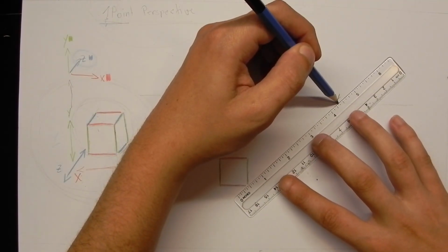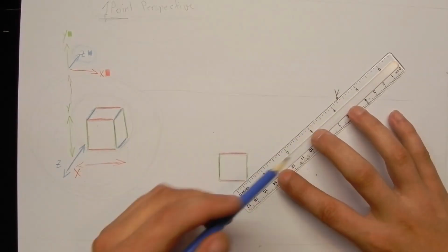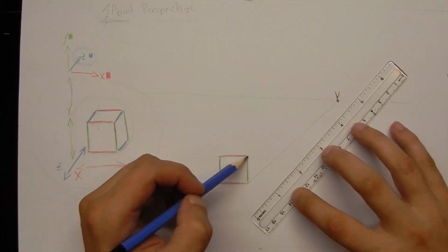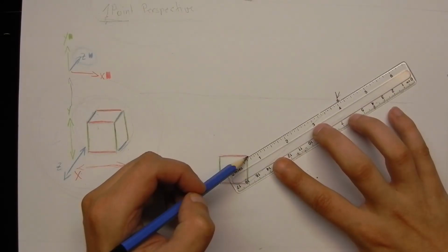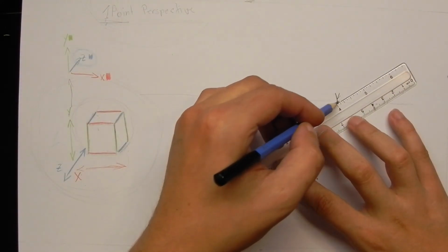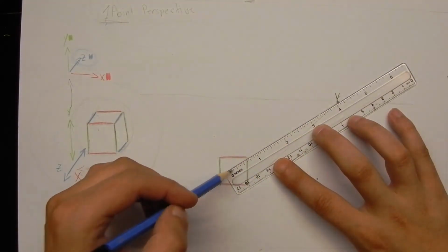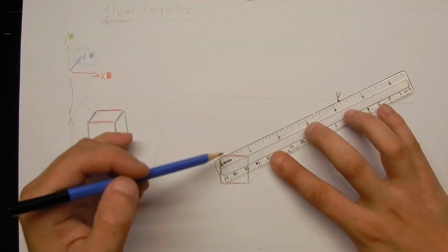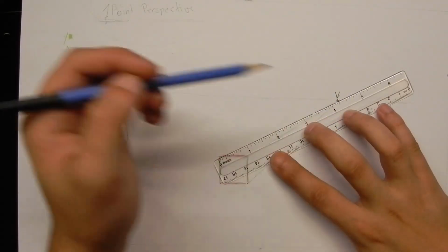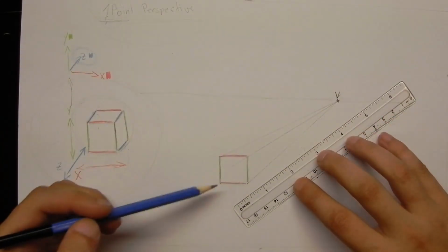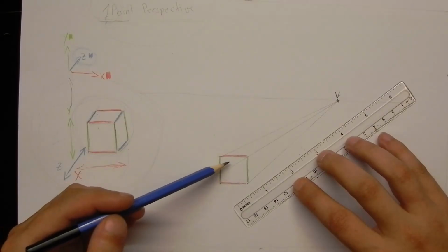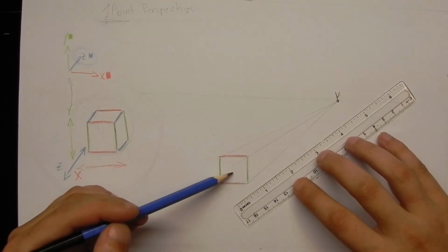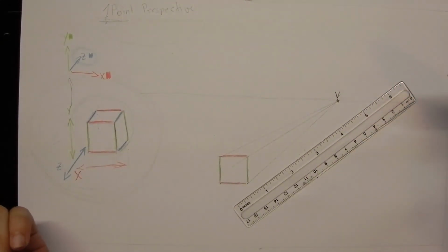I draw along helper lines from the vanishing point toward our first corner. Then we take the next corner, go from our vanishing point down, and the last corner here. We also could draw along to this corner, but since the front surface of the cube is hiding those edges in the back anyways, we just don't need it.